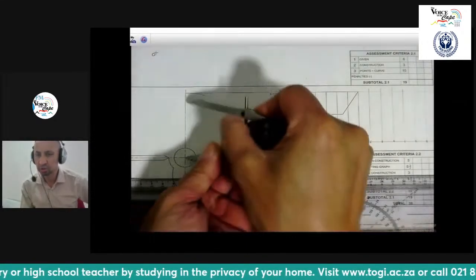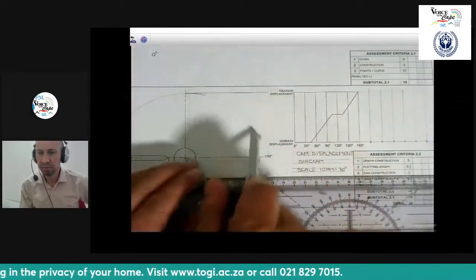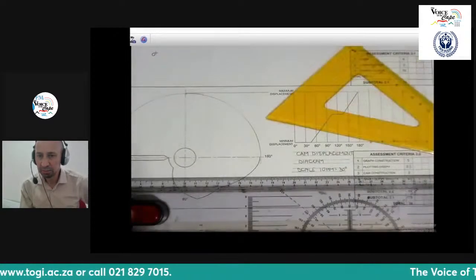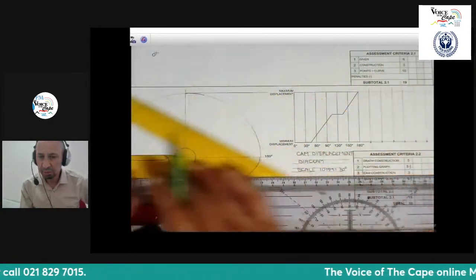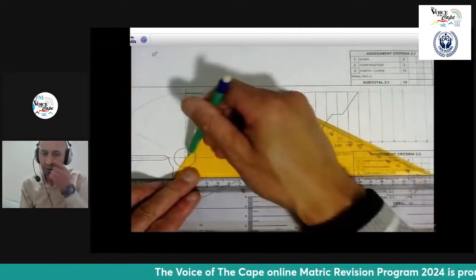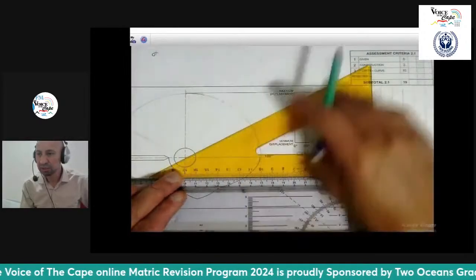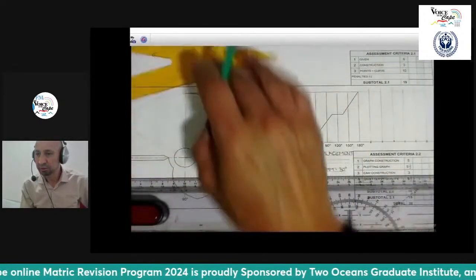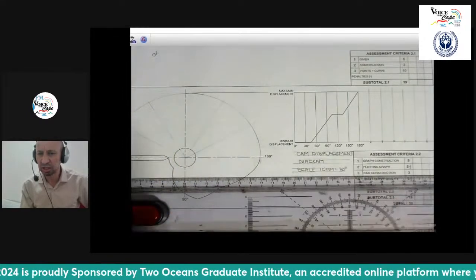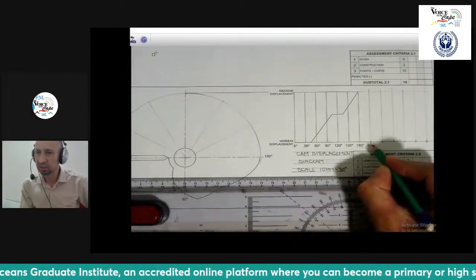So what I like to do is give sort of volume to my displacement graph, my profile, and that is where my maximum is, and my minimum is going to be where the tip of my cam follower is. And those are the divisions that I have. Because I've got 6 vertical positions here, it must match the 6 vertical positions here. So I'm only going to do it this side. I don't need to do it this side because that's completed, and that reflects on this half here.